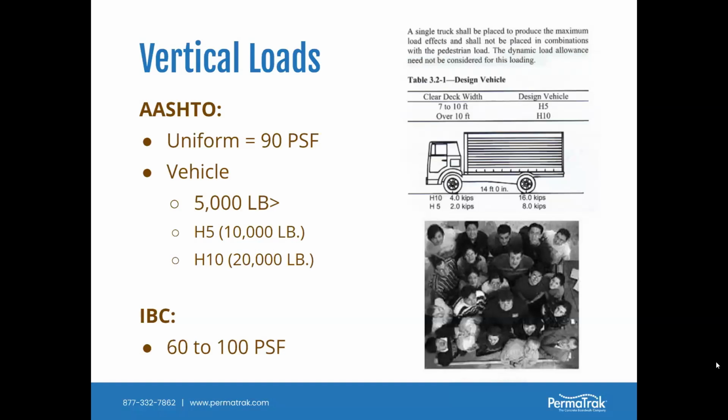You can imagine if you have an observation platform that's being used for a concert or a stage, the floor loading may be bigger, and you could be pushed as high as, say, 250 pounds per square foot per the IBC if you were of certain usage classifications. So it can be heavier. Both generally lead you to about the same answer, but there are some nuances you need to know about each one.